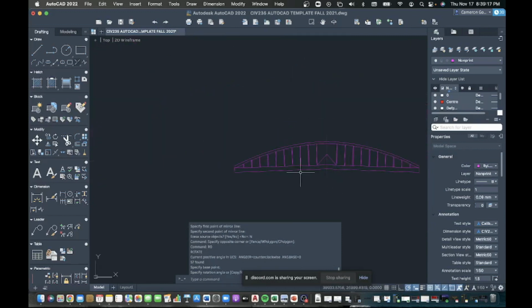And what this has done, that 2 degrees rotation that we did and then mirrored, is it's given a slope to these bottom beams here and here. And this can be useful if you're designing something that allows the water to run off it to the left and the right, or if you're doing a truss bridge or things like that. Slight angles are typical of road details.